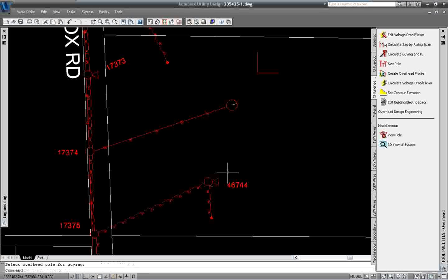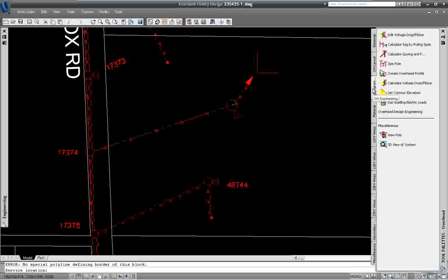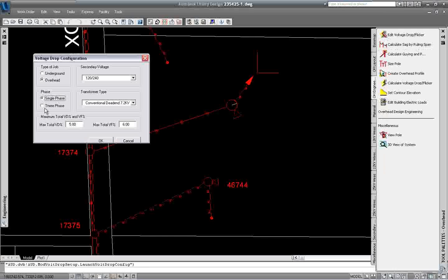So I've got my leads, my anchors. I'm going to go ahead and install a transformer on it. The transformer is just a transformer because I haven't sized it accordingly. Then I'm going to put an overhead service into it out to this load, and take a look at that load. I'm going to design this for 3-phase overhead, 120/208. Transformer connection is a grounded Y overhead. Okay, so I'll do that.